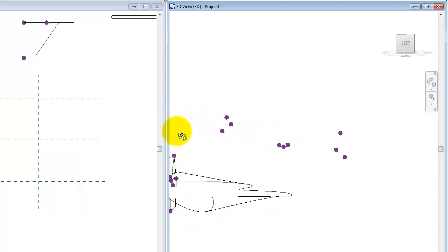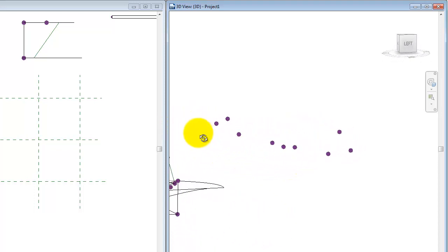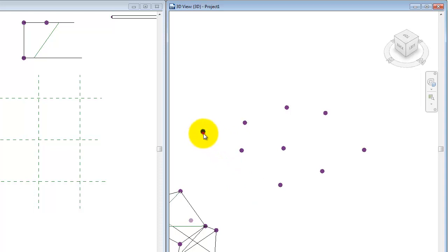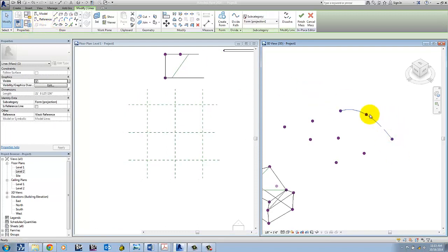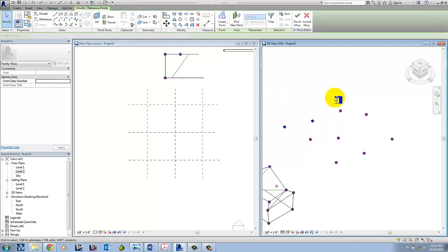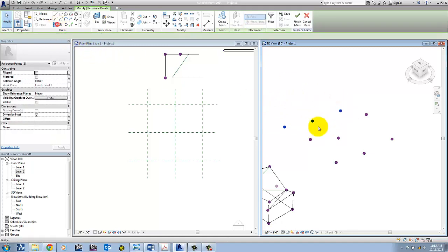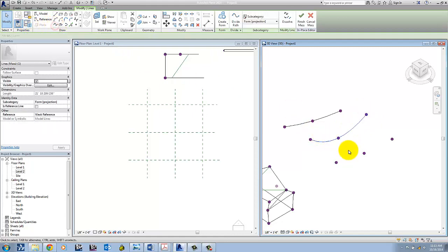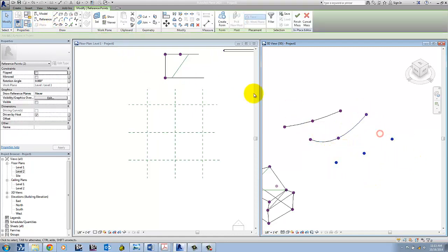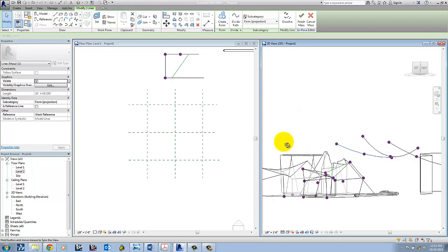Okay, so you can almost see the mesh they're doing. Basically what I want to do now is select 3 of them. It doesn't matter which 3, it's going to get you the same surface. We could select these 3 and create a spline through them. We could do it the other way, select these 3, do a spline through them. Select the middle 3 and do a spline. And the other end and do the spline.